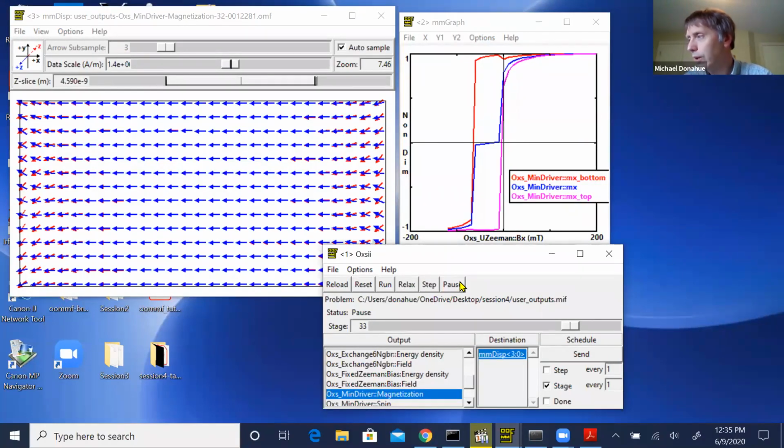Is the norm 1 really needed in the file vector field? It is not needed to set up initial magnetization. The initial magnetization will do an auto scaling. So if you're using a file vector field to set the initial magnetization, which is how you usually use it, then no, you do not need to specify norm 1. If you're loading it into something else and you want it to be normalized, you need to do that. If you don't want it normalized, you want the raw field values coming in, then you don't use it. Okay.